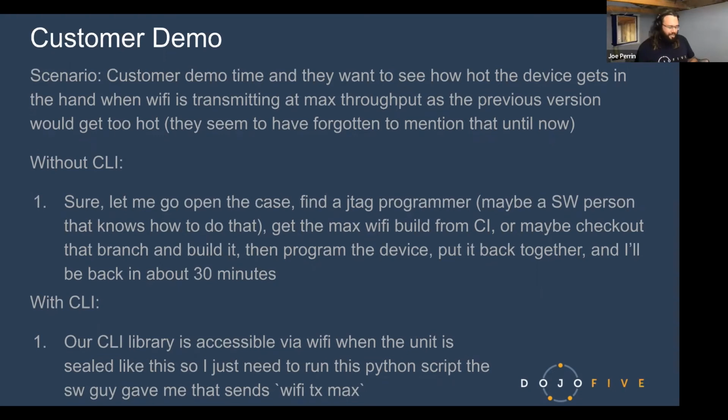But if I had a CLI that just said LED set brightness X, I could have done it right there. And that's probably how you would implement something like that. You wouldn't say, oh, here are the steps. You'd say, here's the PWM duty cycle. Here's the luminance value, and specify it that way.